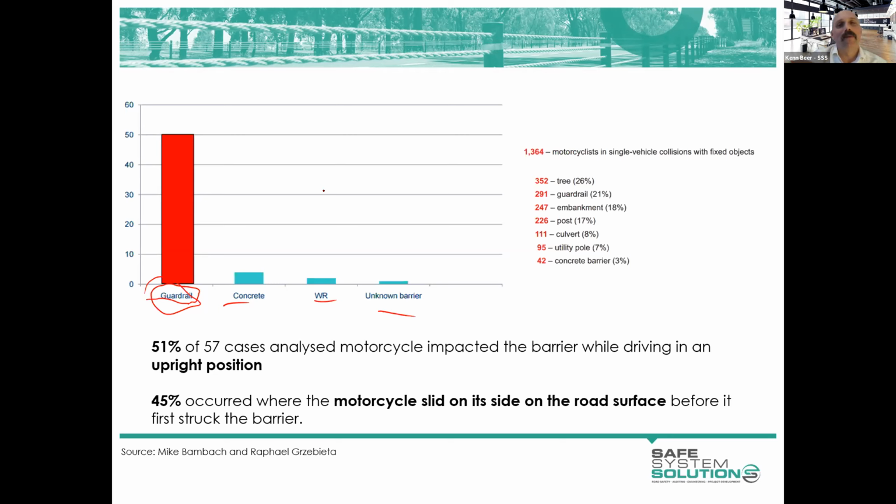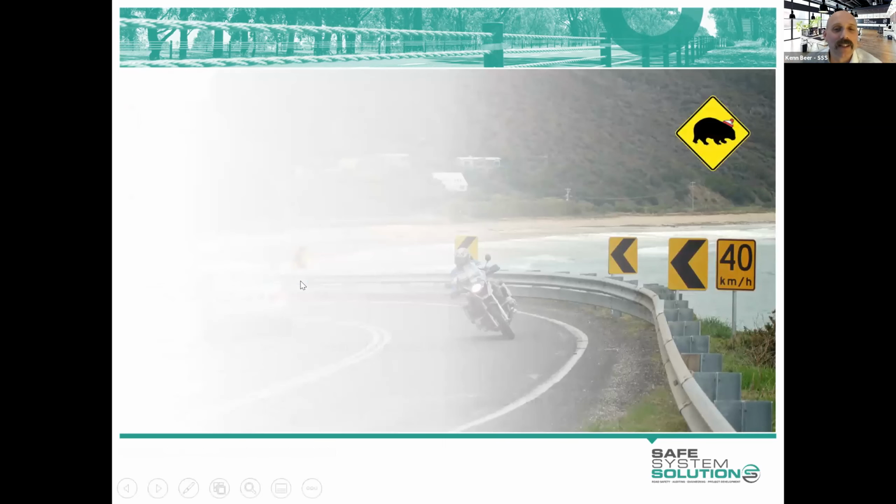You saw that there was a minimum radius of 200 for a wire rope system. That's basically, if you're looking down on it, that's your system. If you had a wire rope of that, you had a terminal and terminal, and you tensioned it up, tension and tension and tension, and it's just going to pull the posts and it'll try to go into the middle of the road. So that's why we don't do it. So yeah, it's not out there on those touring routes as well. So certainly some really good points in there about the curves. So that's, I think, interesting for us to note.